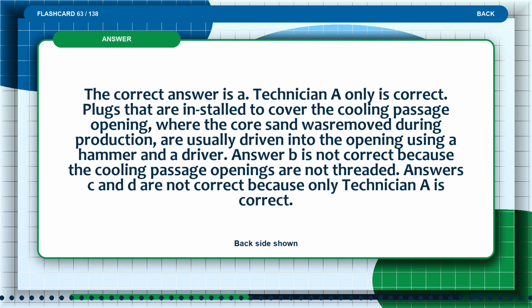The correct answer is A. Technician A only is correct. Plugs that are installed to cover the cooling passage opening, where the coarse sand was removed during production, are usually driven into the opening using a hammer and a driver. Answer B is not correct because the cooling passage openings are not threaded. Answers C and D are not correct because only Technician A is correct.